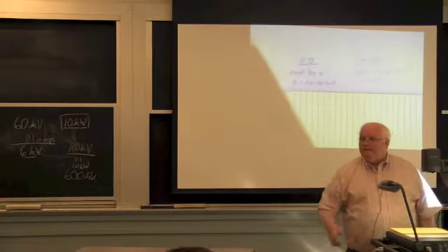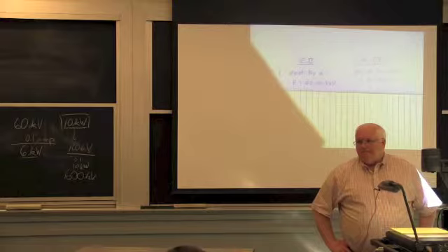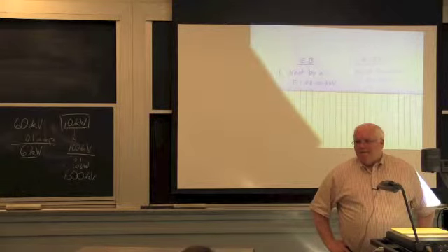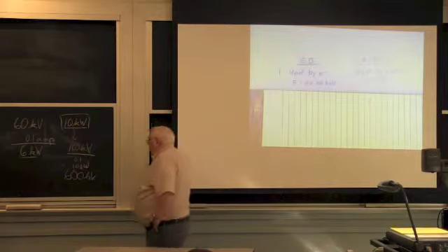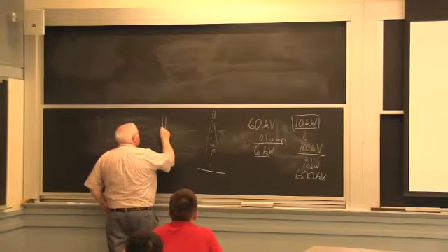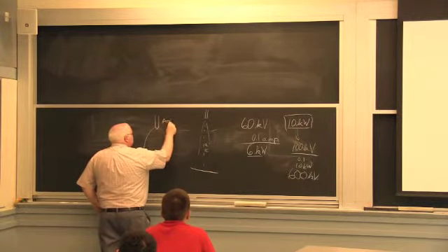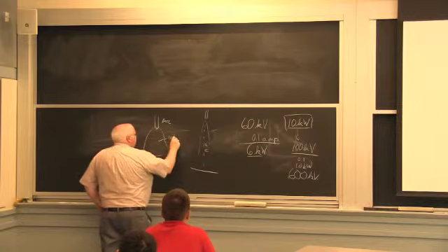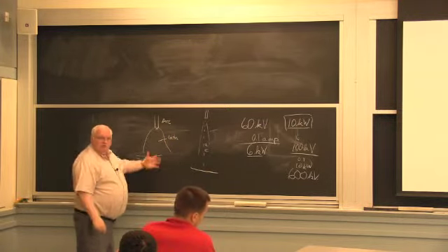But yeah. Question. So, what is the major difference between an arc and electron beam welding? Just the vacuum voltage? The arc weld is in a gas in the atmosphere. I guess I should have explained this. So an arc weld, we got 1 atmosphere of some gas, whether it's CO2, helium, argon, oxygen, whatever.